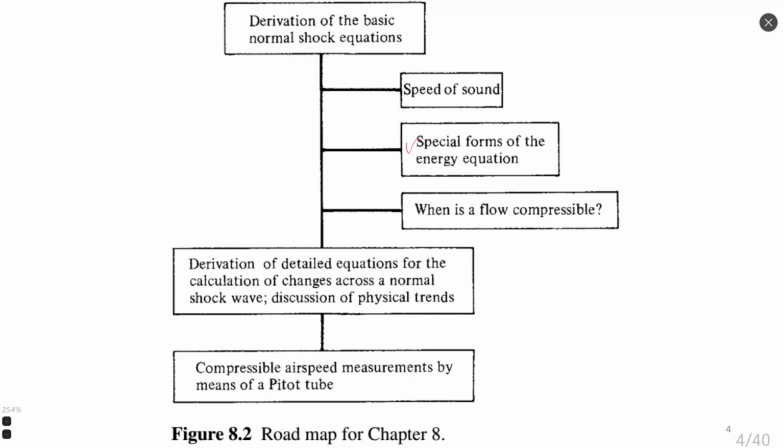And when the flow is compressible, we can give a definitive answer based on a flow model. Before, we had some definition of a compressibility coefficient, and we said that flow is incompressible at Mach less than 0.3, but here we will prove numerically why this number is valid.